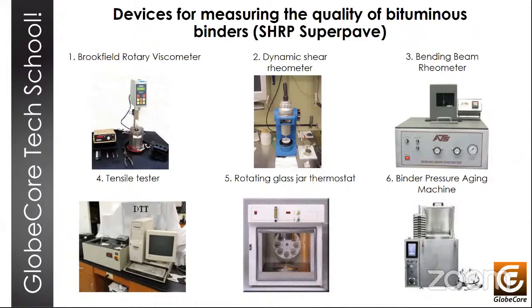To assess the strength of bitumen at high temperatures corresponding to a particular zone, the complex shear modulus G and the tangent of the angle of mechanical losses are determined using a dynamic shear rheometer, which performs sinusoidal oscillations in a plane-to-plane pattern with a frequency of 10 radians per second. To assess the crack resistance of bituminous binders, several indicators are used.